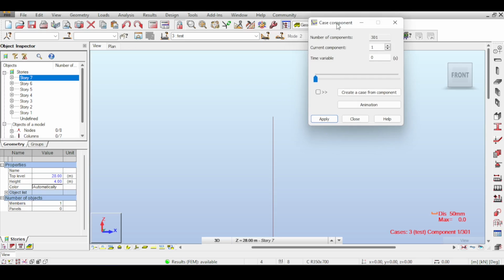Now let's take a look at this. If you scroll through this, you can see the force increasing. I'm using the arrow keys to cycle through the time steps. So while I'm moving to the right side, you can see that the time increases by 0.5. And you can see that my force is increasing, keeping for 3 seconds, and you can see the structure is vibrating now, which is amazing. You can see all the structural dynamics happening here. The force dies, which means the structure swings back and then is held in place with the other force. And then the force dies again, and you can see that the structure swings back into place.